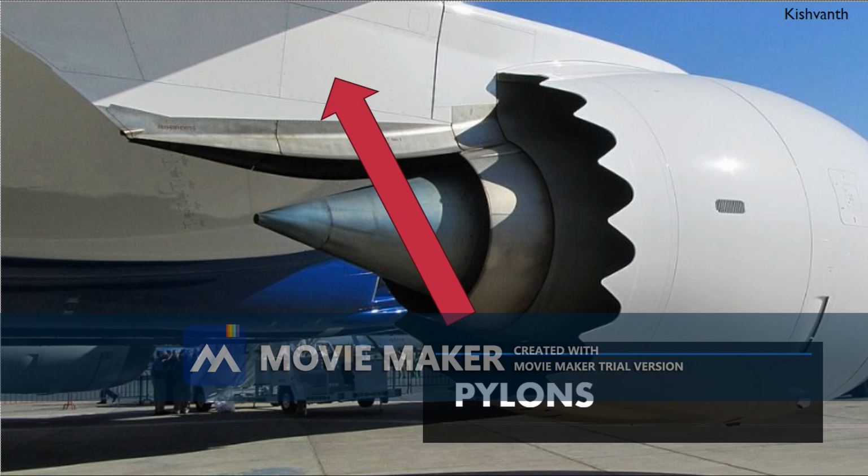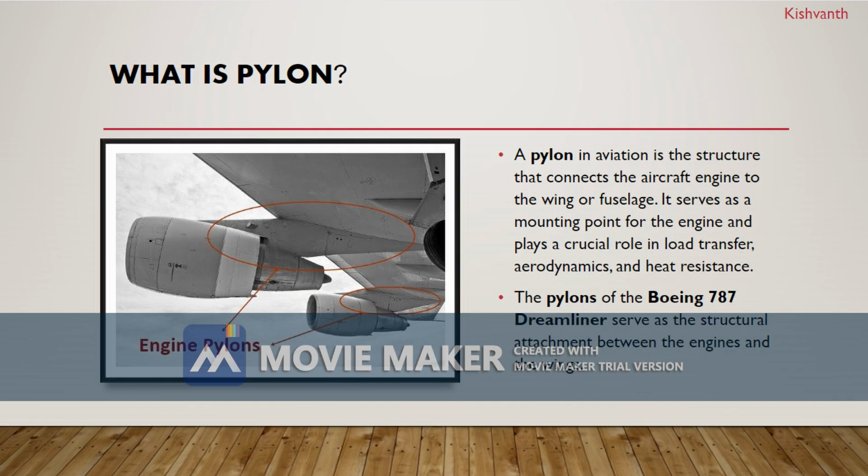Now I'll be talking about pylon. So what is pylon? A pylon in aviation is the structure that connects the aircraft engine to the wing or fuselage. It serves as a mounting point for the engine and plays a crucial role in load transfer, aerodynamics and heat resistance. The pylons of the Boeing 787 Dreamliner serve as a structural attachment between the engines and the wings.